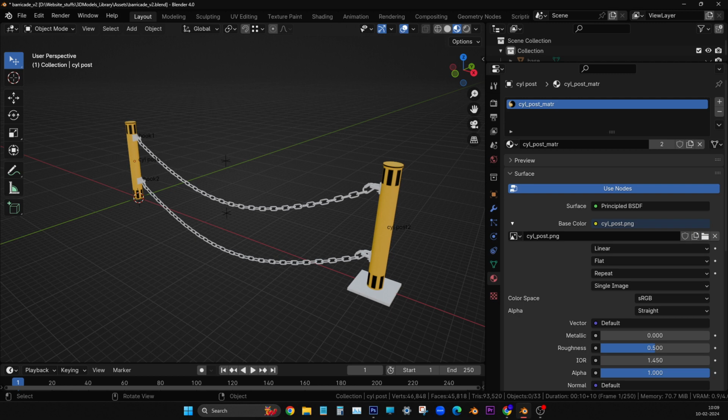So you can scale it also for your visibility. You can scale the light. Press S on the keyboard and then uniform scale. White circle. Uniform. Bigger. Still bigger. Make it even bigger. Yeah. Now you place it a little like a ceiling light. Select the move and move it up. Still more. Yeah. Enough.